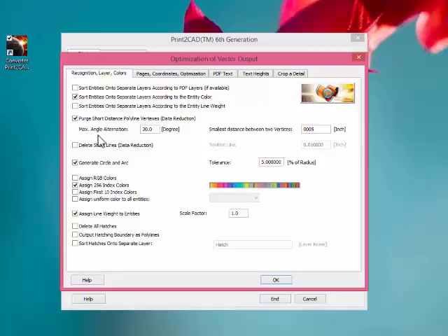So of course you are going to want layers in your final DWG, and we have 3 different options for actually making that happen for you. Of course, if you have PDF layers, we'll be glad to keep them for you. Simply check the very top box. If you're not so lucky as that, we can generate layers for you based on entity color, or based on entity line weight, and we can even do color and line weight simultaneously if you'd like.